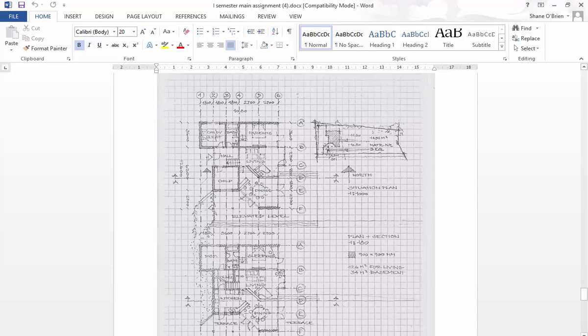It's an easy way to draw it on squared paper, because then you can say each square is relevant to 900 millimeters or whatever. And all construction materials have some kind of relationship to a 300 millimeter module. So if you're working in 900 millimeters, you can be pretty sure that you can get products off the shelf without having to cut them that will work with this house. So that's why you often use squared paper to make a layout like this.